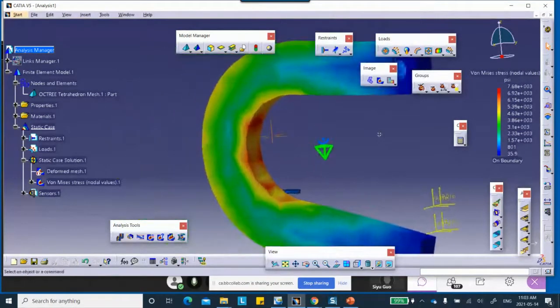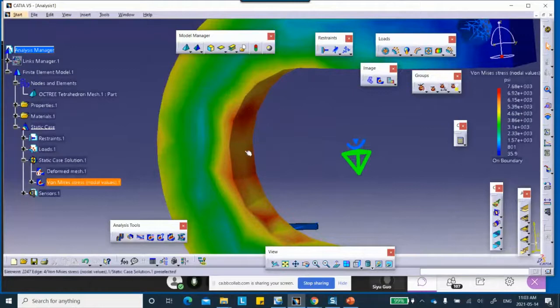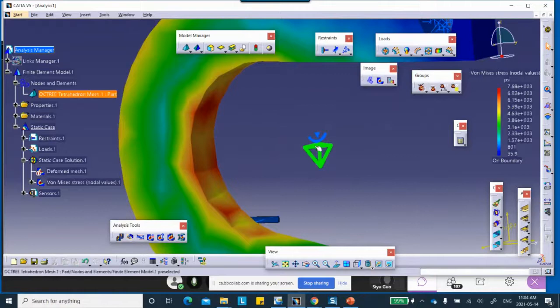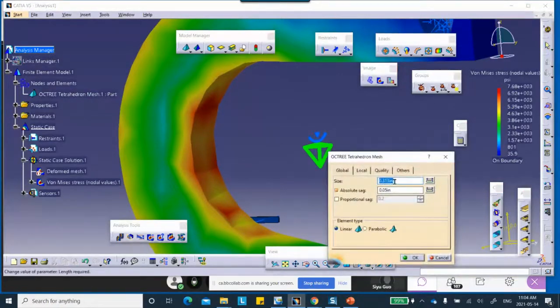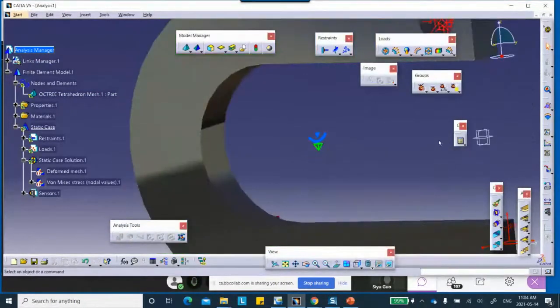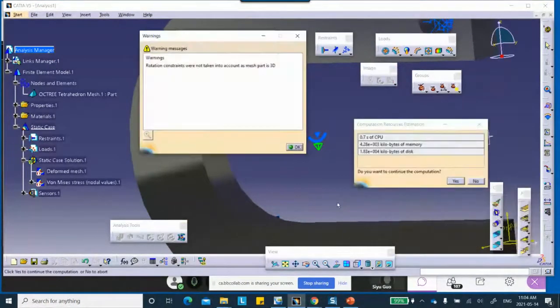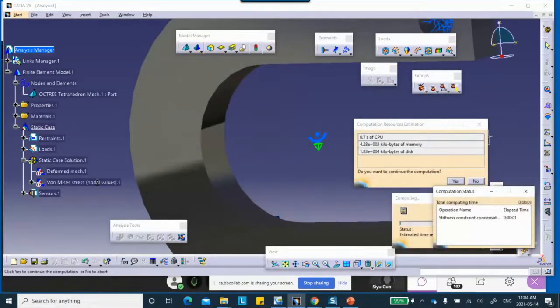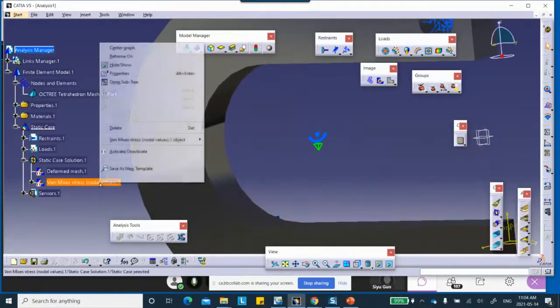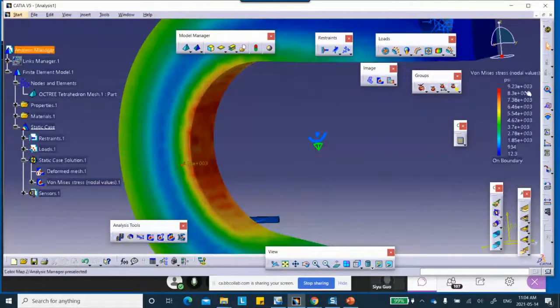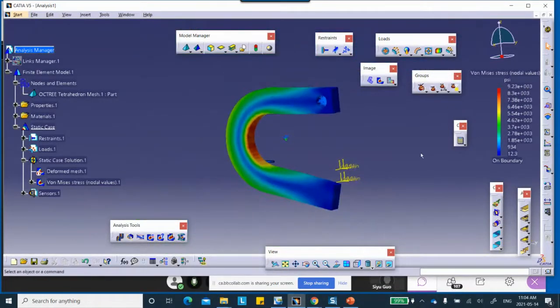The other thing is that with linear element, unless the mesh is very fine, you can see this patchiness, which tells you that the mesh is not small enough. So let me go ahead and change this to a smaller size. For example, 0.1, how about that? 0.1, still linear, bad. But let's see what happens to the stress. It was 7,200 something. Now it's 9,000. You see that the patchiness is kind of gone. And we get what we expected from the parabolic one.